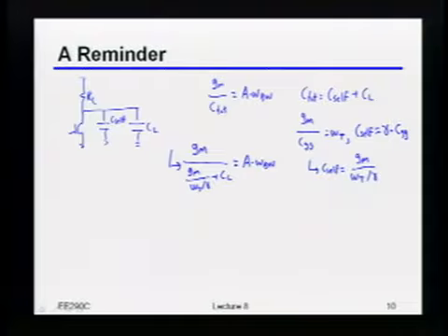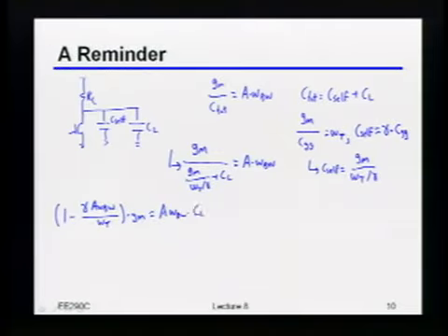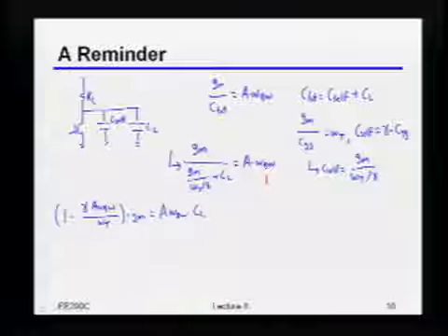So from here, I'm just going to rearrange the terms a little bit. I'm just going to group all the GMs together. And if you do that, then you just get something like (1 minus gamma times A omega bandwidth over omega t) times GM is equal to A omega bandwidth times the actual explicit load cap. Okay? And by the way, all I really did there was just pull this up to the front and then subtract it off onto the other side. And then just regrouped it in terms of GM.